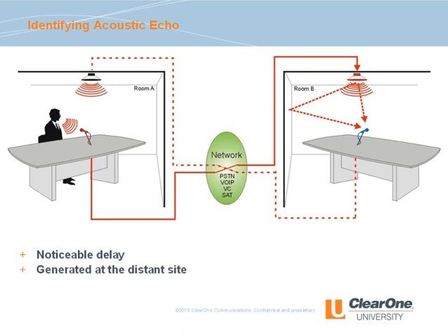It is also important to note that acoustic echo is generated at the distant site. If I'm in room A and I hear an acoustic echo when conferenced with room B, room B needs the acoustic echo canceller. Because of this, another indicator that the echo you are hearing is acoustic echo is that it stops when the distant site mutes their microphones.